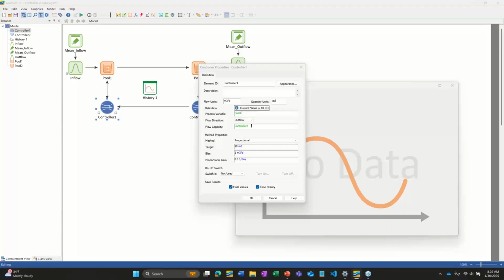And then I do this kind of different thing where I say, okay, I don't want to just pump the capacity of whatever this thing can pump at. I don't want to just go on or off completely. I want to control this flow capacity, and this capacity is being controlled by the other controller. So essentially, it's like overriding it pretty much. So that's how the overriding happens, and that's how this whole controller in series can work in this type of a case.